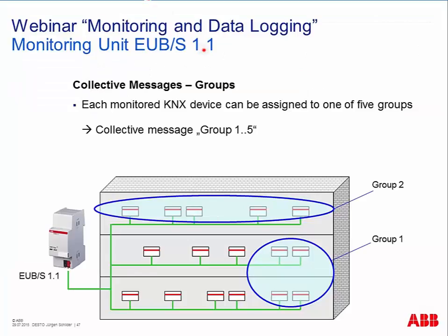Yeah, so 4 different ways. In principle you can choose what you want. Physical address, yeah, you can take in every case, because maybe you have adjusted in your line coupler that you block any physically addressed telegrams. So any downloads are not possible anymore intentionally. Of course, then you cannot send also the telegram poll physical address anymore, because it will be blocked as well.